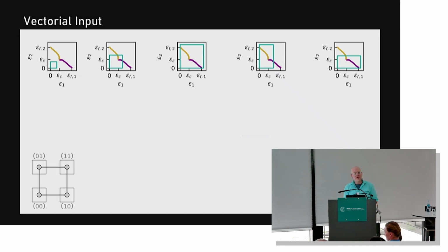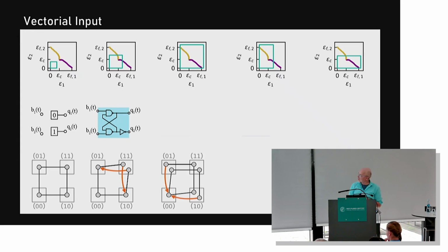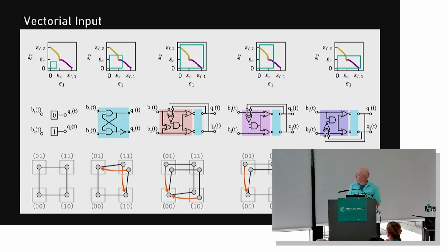If you start like this, it is a completely trivial circuit, so your input and output are the same. If you do like this, this is the one I just showed you. What I didn't show you is that this is precisely the same functionality as an RS latch, so it's a single bit of memory. If you drive it slightly differently, you shift the location of these transitions, and you get something like an RS latch with some additional logic there, and you can play with that.